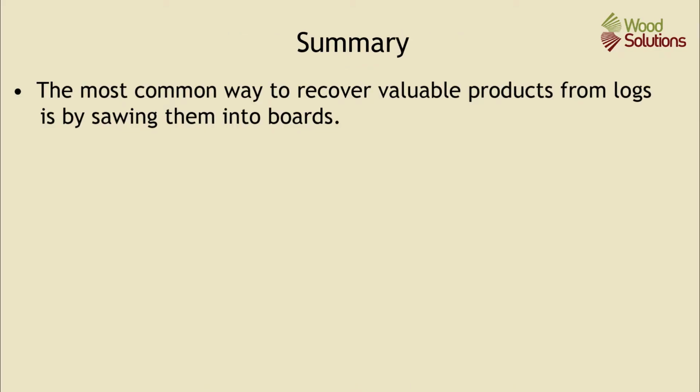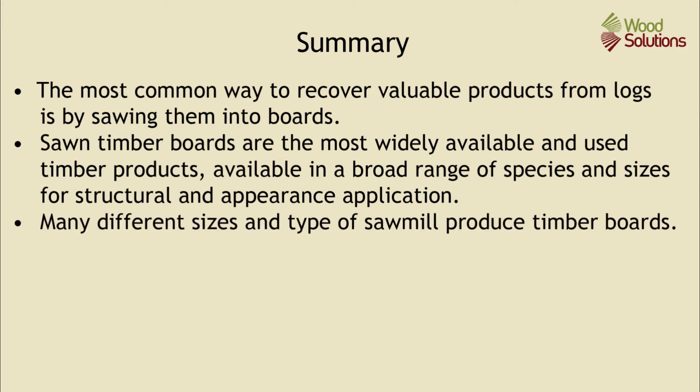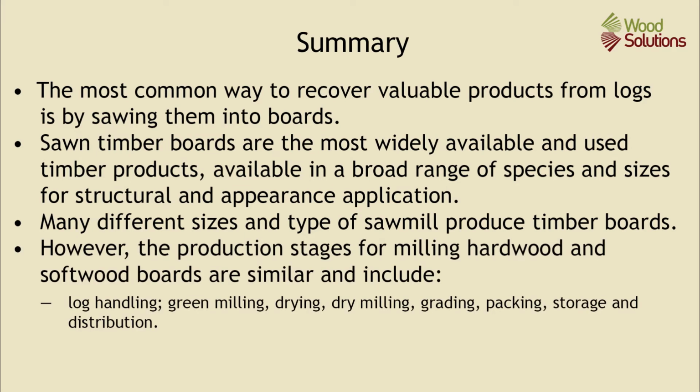In summary, the most common way to recover valuable products from logs is by sawing them into boards. Sawn timber boards are the most widely available and used timber products. They're available in a broad range of species and sizes for structural and appearance applications. Many different sizes and types of sawmill produce timber boards. However, the production stages for milling hardwood and softwood are similar and include log handling, green milling, drying, dry milling, grading, and packing, storage and distribution.